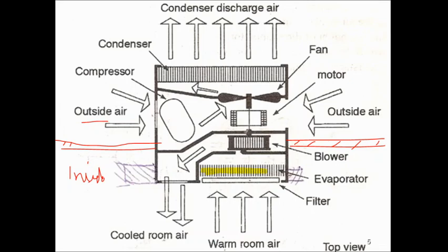It does not matter how much temperature you set on your thermostat, because it will take a fixed amount of time before the air temperature reaches it. So you have to wait for it. So it is better to set the temperature quite close to 22 to 25 degrees Celsius. It will give you maximum efficiency in this temperature range.